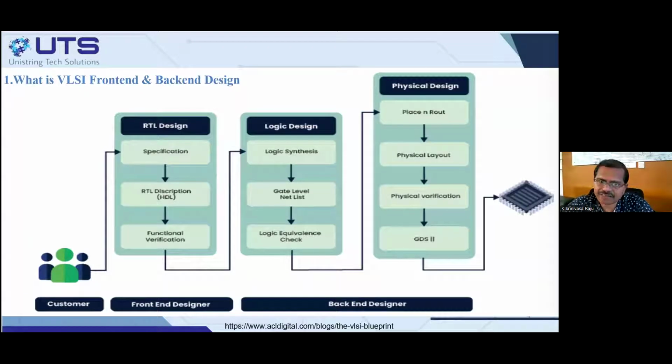Okay. So RTL basically is like you are trying to say how the data is moving across the registers. These registers are nothing but the registers and counters that you studied in your VLSI digital courses. Invariably, any digital design, when it is synthesized, if the design is described in VHDL or Verilog, if it is describing your digital design in the form of how data is moving across registers, then only it is synthesizable.